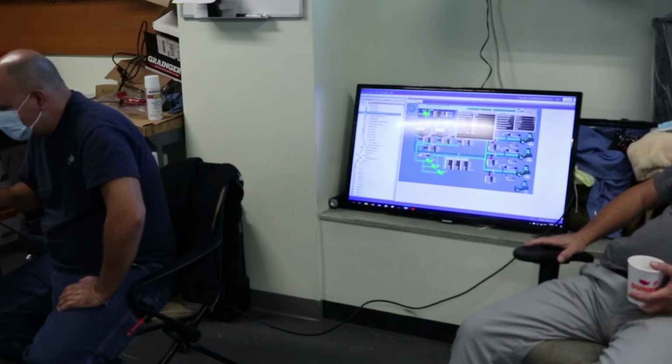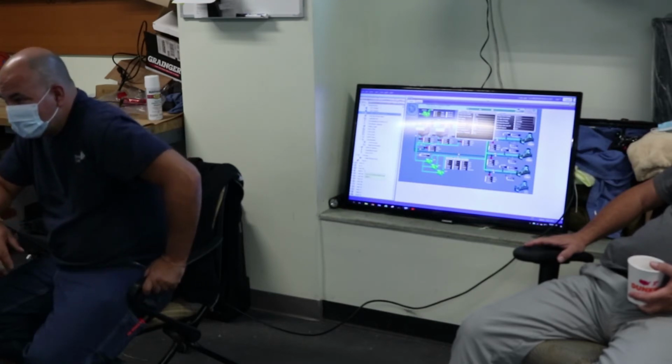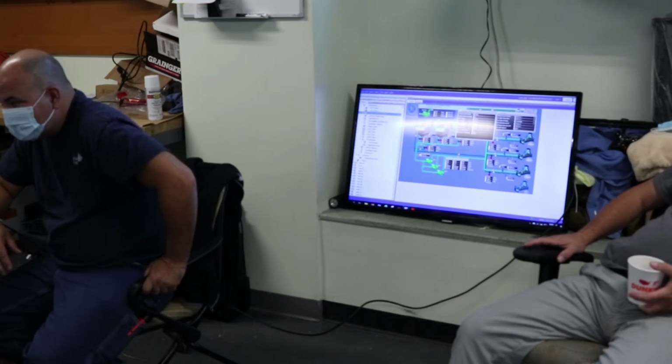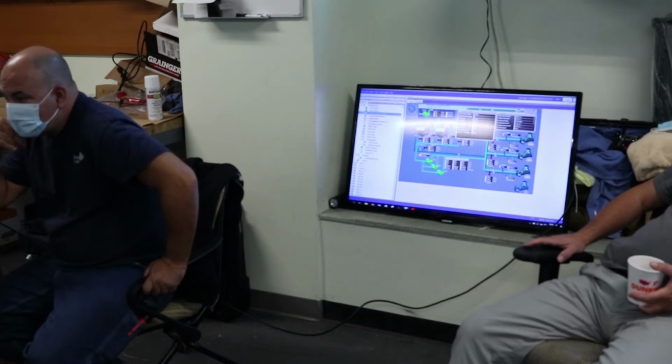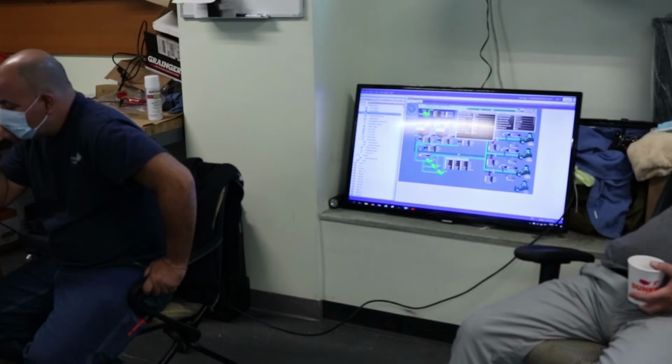Okay, what do you think? Should the boiler be replaced? Oh yes, it should be replaced. But do what Robert did: have him go look at building 2 and do the crossover so you can use boiler 2 for heat and domestic hot water. We've got a crossover in the backup, with spools and a valve, while they're putting the boiler in. That way you're only down for a day, maybe 2, without hot water. Then you do the crossover, we get boiler 2 running, and they'll have hot water while they replace the boiler.